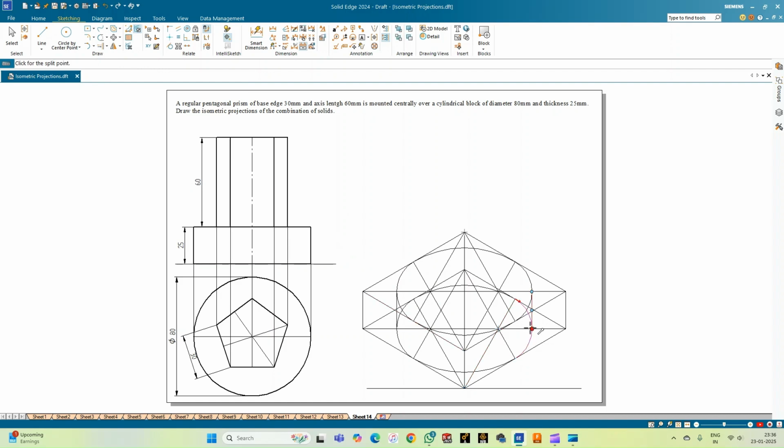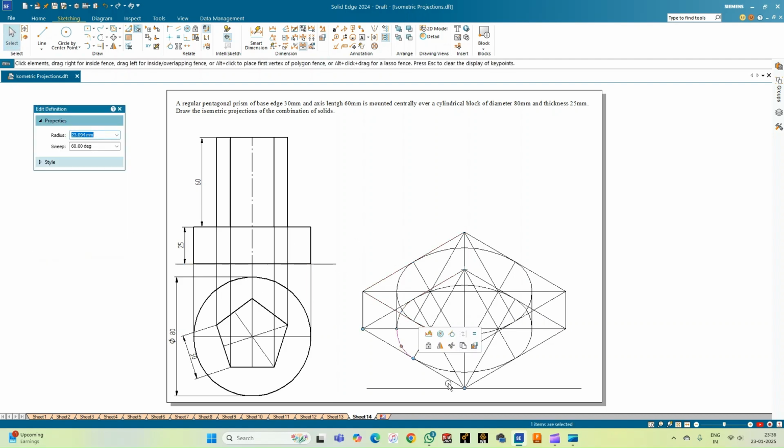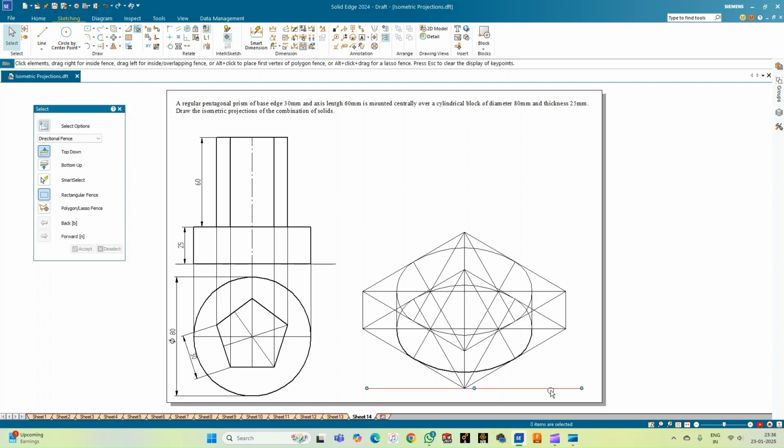Select the arc and just ensure that it is a separate entity now. Select this arc and split it at this point. Now let me select these pieces and make the thickness as 0.50. All this is available within the line options. The moment you select the arc, you get all these accessories.